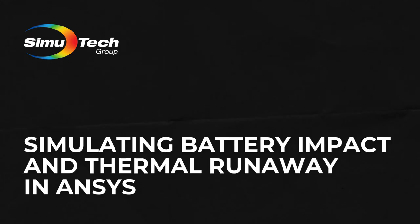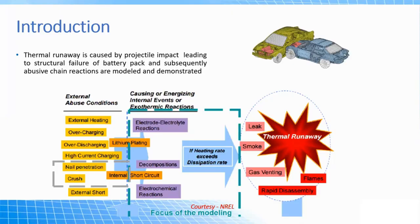So, some quick introduction to battery and thermal runaway. Thermal runaway in batteries is caused by some sort of external abuse that can be from external heating, overcharging, or, like what I'm going to show you today, some sort of impact. This causes some internal events, and specifically exothermic reactions within the battery, which cause the temperature to increase. And if the heat generation of those reactions exceeds the rate at which the battery can dissipate the heat, then you lead to thermal runaway.